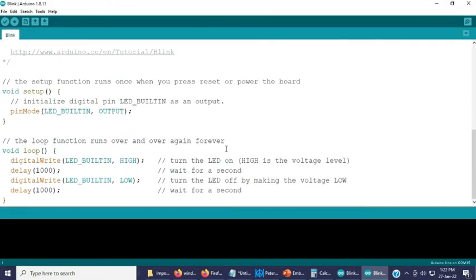When you run this program in your Arduino, most of you might have used this kind of program, the basic blinking program in the Arduino board. Can you stop your program here or here? Can you stop your program on this line to check whether the LED is on or not? No. Can you stop it after that? No. That means no, because this microcontroller, the Atmega 328, which is used in this Arduino board, does not have the feature of debugging circuits.